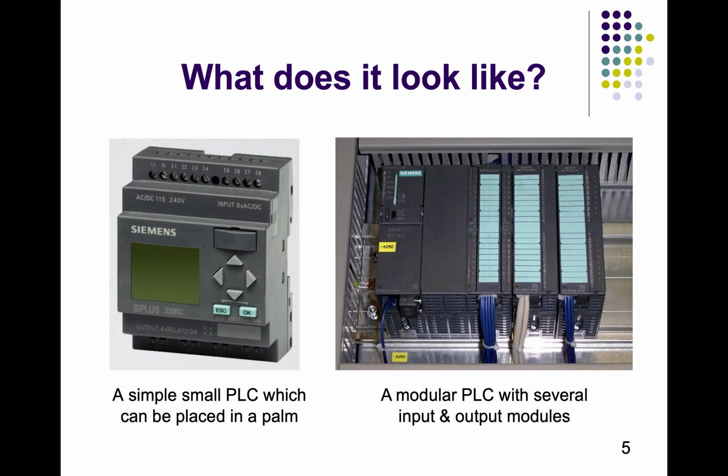What does a PLC look like? A PLC can be as small as can be held in our hand, or it can be a modular PLC to which we will keep on adding new input and output modules. So in the fixed PLC, there are a fixed number of inputs and outputs, and we cannot customize the number of inputs and outputs in that system. But a modular PLC has enough capacity. It is like a big computer where you can add more and more inputs and outputs.